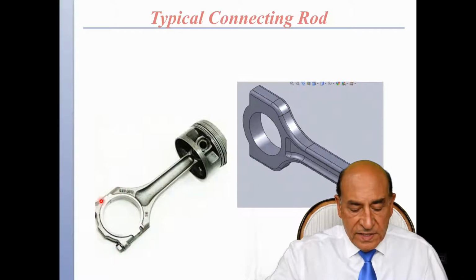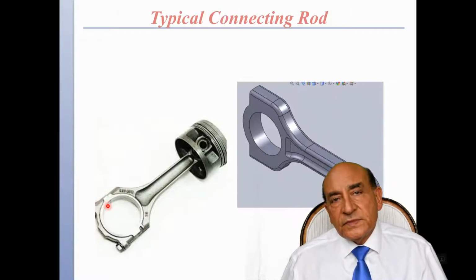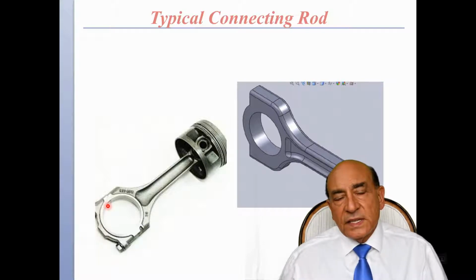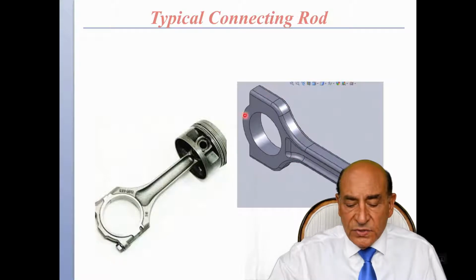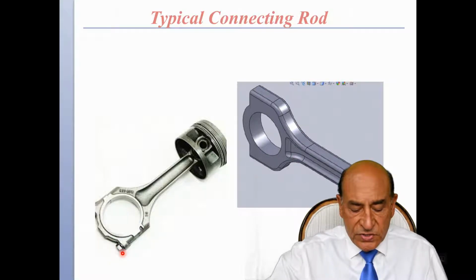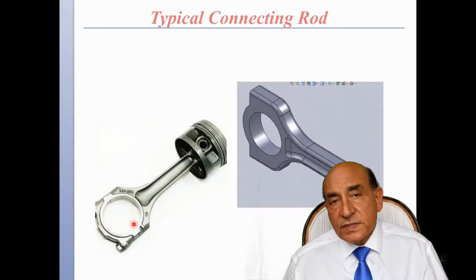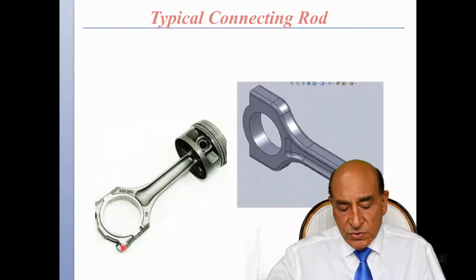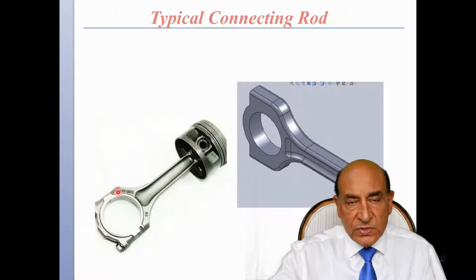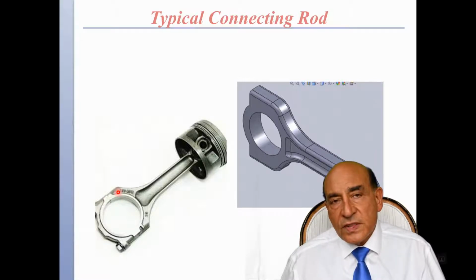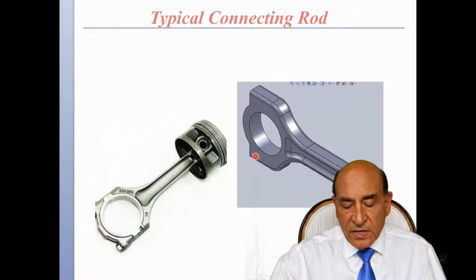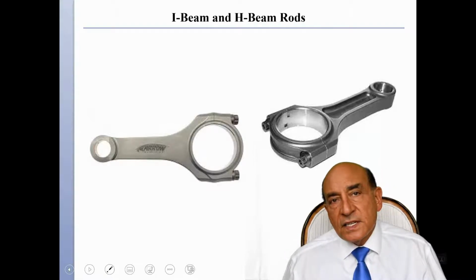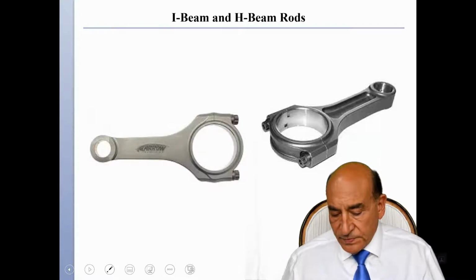And then you have the two bolts that connect to the crankshaft. Now, in doing 3D modeling, we're not going to produce detailed models for the bolts, because that will take more time and more detail to do the stresses and the distributions of forces and so forth on the bolts, and therefore we're going to take it as a continuous system, as you can see in here.